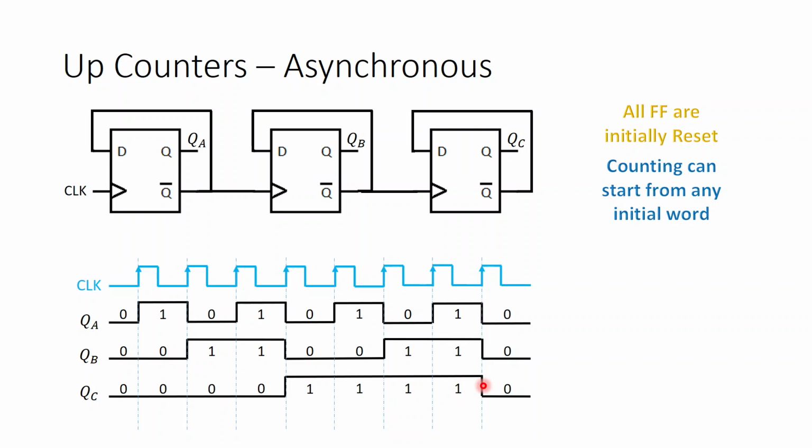So now you can draw up. So you see, again we get 0 0 0 here. That means the same operation will repeat after this clock cycle. So you can end here, and now you look at the sequence you have got.